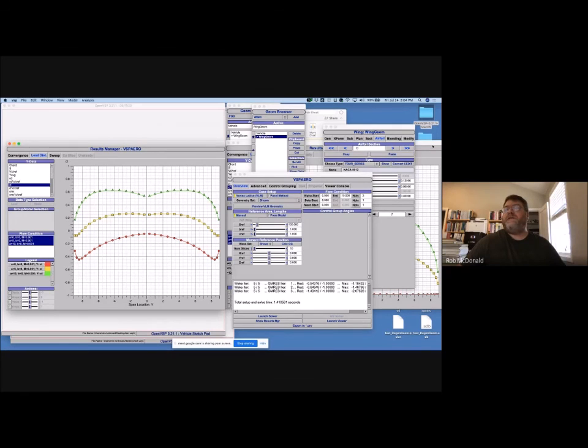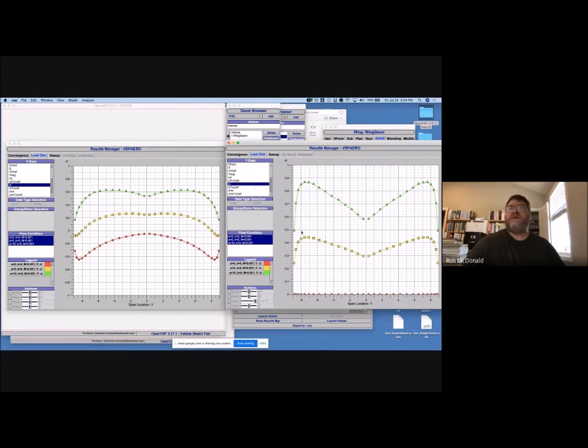And if we look at the other wing that's not twisted, this is a much worse case, because here, again, if we look at the CL and we say it stalls at 0.6, first off, much more of the wing is stalled. Now you could say, oh, well, we're getting a lot less lift because we've twisted it down 10 degrees, and that's true.